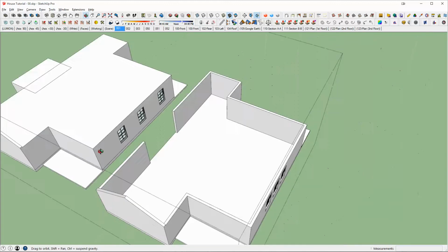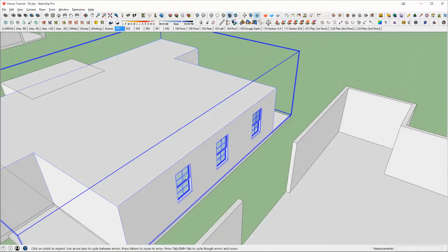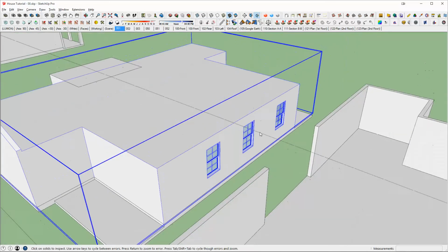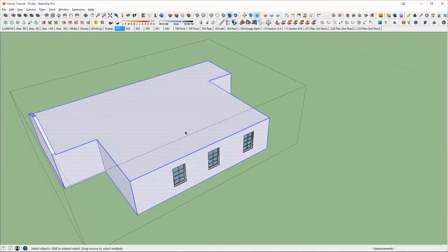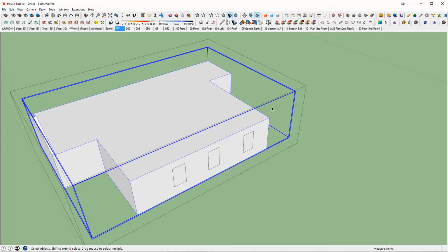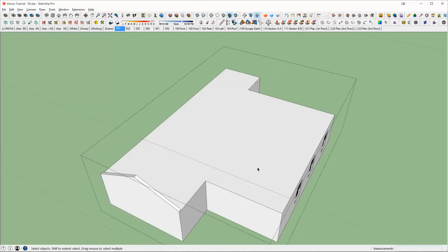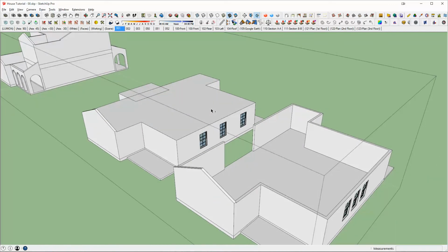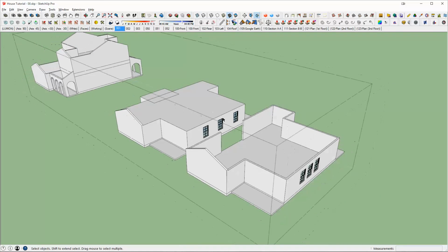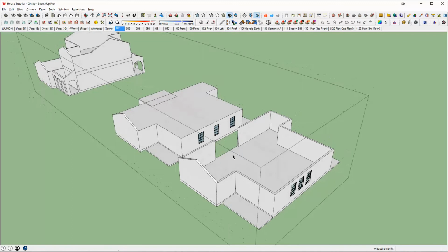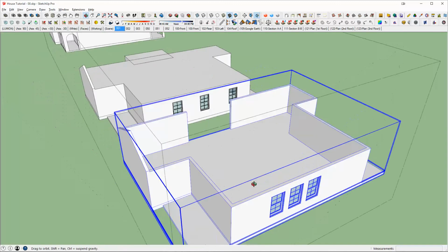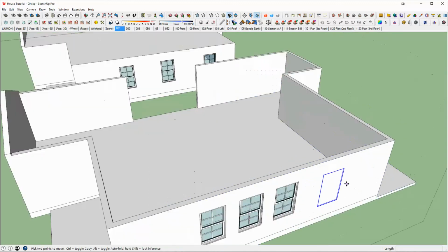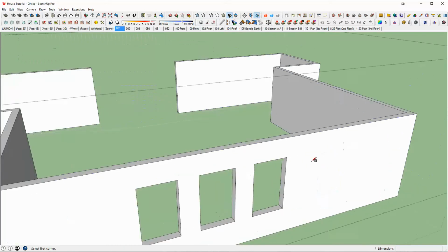it's telling me this is not a solid, and it's not a solid because of these windows. These windows render it no longer a solid, and if I come back in here, click everything, turn it into a solid, then my windows disappear. So that's kind of the disadvantage to the shell method, is you can no longer do solid modeling, and at least in the way I've moved forward and found a lot of speed in being able to create models is through solid modeling. I've adopted this method of simply adding in where a window goes, and then just coming in